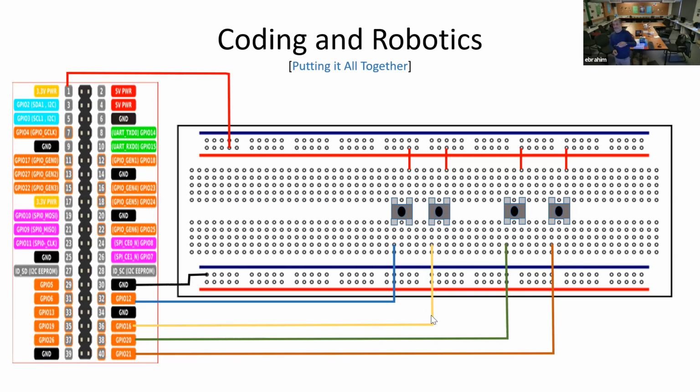From an engineering point of view, it's very important to understand your processor and the I/O you're plugging in, so that you don't have incompatibility. If you do, you'll blow up the microcontroller or something. That's why you have to read the specification and understand it.